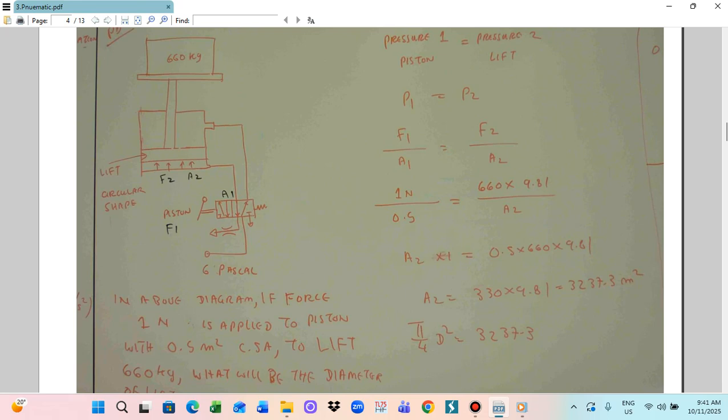If you utilize a larger area to carry the load, more force can be lifted. Similar to the hydraulic jack you see in a car workshop. A hydraulic jack means a small motor drives a big piston, compressing the hydraulic fluid. Those hydraulic fluids are multiplied in the other larger lift, which carries the load. By this way we can multiply the force. This is why, in process control systems, force and pressure measurement is an important aspect.